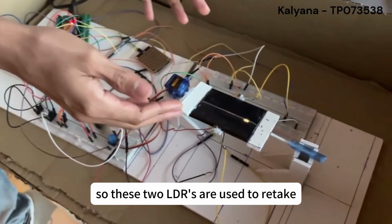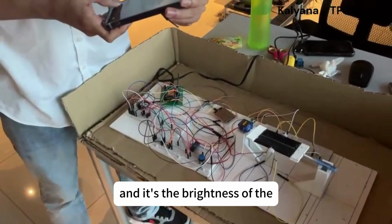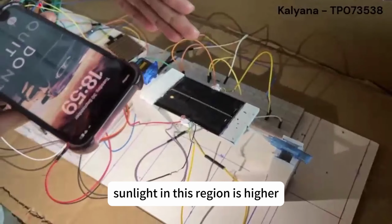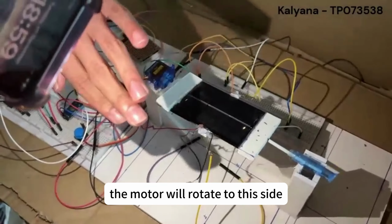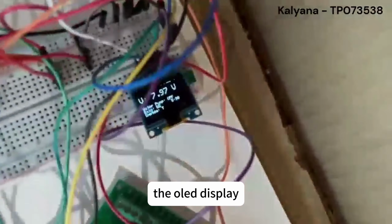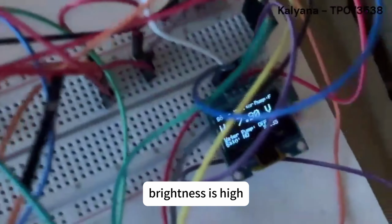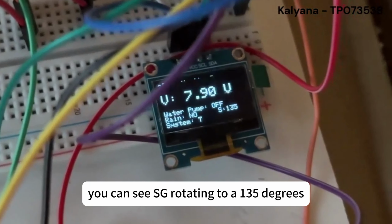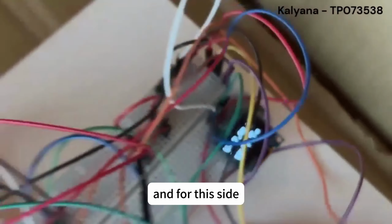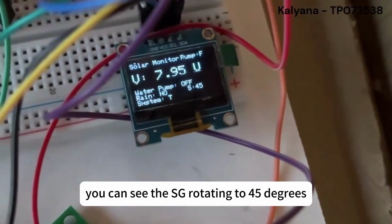These two LDRs are used to detect the brightness of the sunlight. If the brightness of the sunlight in this region is higher, the motor will rotate to this side, and for this side it will rotate to this side. You can see in the OLED display, for this side, if the brightness is high, you can see the servo rotating to 135 degrees, and for this side, if the brightness is high, in the OLED display you can see the servo rotating to 45 degrees.